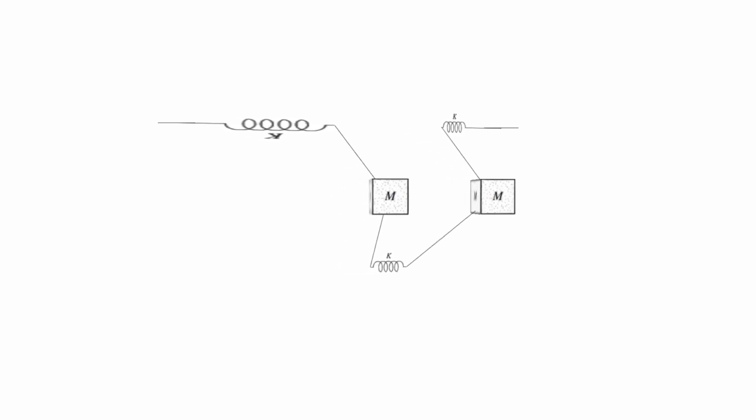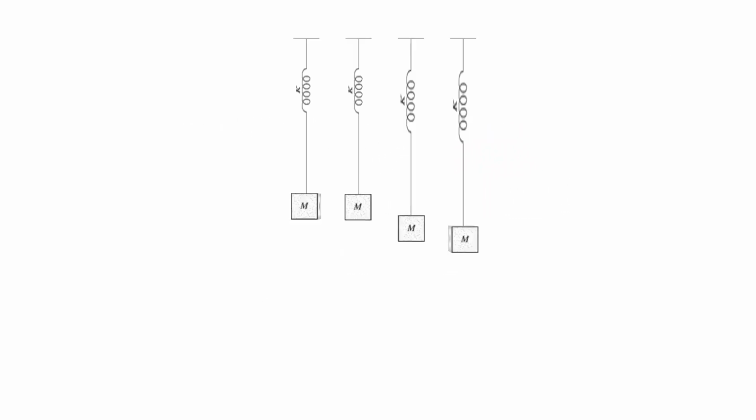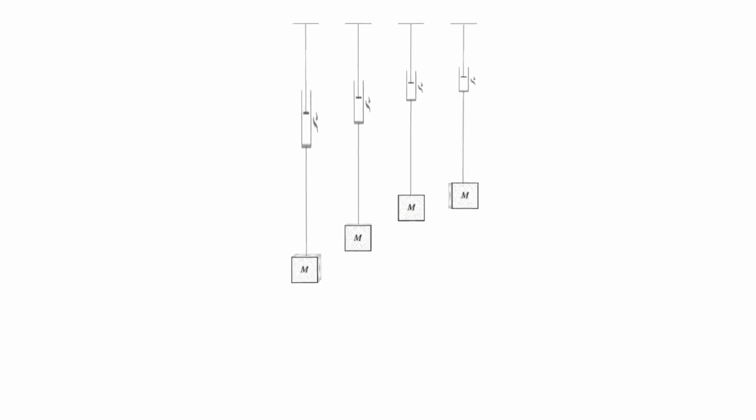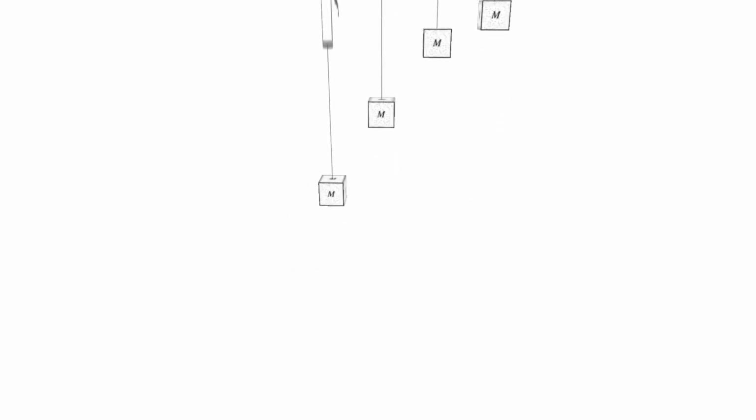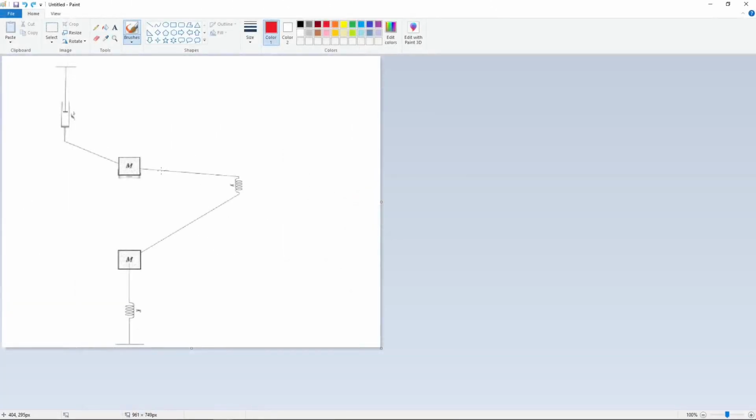They're defined as any system of masses and connections where connections can be a spring or a damper. Springs are bouncy and store motion, while dampers are sticky and restrict motion. Masses have inertia and only move when disturbed. Connections can be to other masses or ground, which is an unchanging reference point.